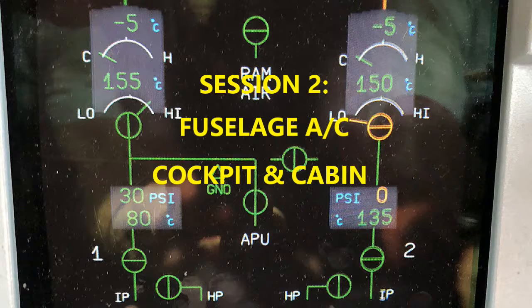Okay, about the flow control valves, just so you know the orientation, they are installed upstream of the air conditioning packs, and they're going to control the quantity of air supplied from the pneumatic system to the air conditioning packs. So that's your go-between from the pneumatic system to the packs: these flow control valves, one for each of the systems. As far as the controls in the cockpit, the airflow is selected by the Pack 1 or Pack 2 push button switches. So when the pilot is selecting either one of those, he's controlling those flow control valves by doing that.